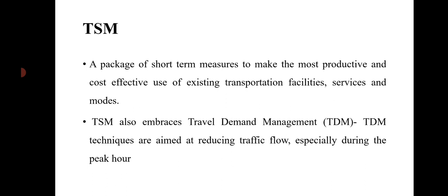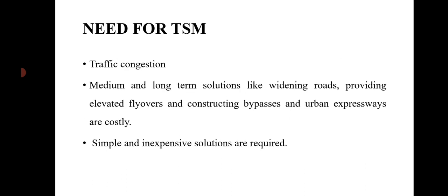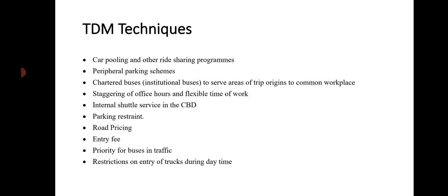It also embraces travel demand management. So, our aim is to reduce the traffic flow, especially during peak hour. So, this TDM or travel demand management techniques, they are aimed at reducing the traffic flow by adopting certain restrictions or certain techniques. So, what is the need for this TSM? I told you earlier itself. There is so much congestion in our streets, and the long-term or permanent solutions are very costly. So, we need to go for simple and inexpensive solutions.